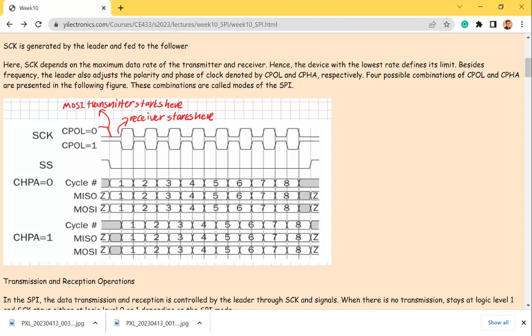Put the PN junctions in there and hold the charge using capacitors, and then send everything out to the ADC to digitize it. And we would have to implement some digital ports on the chip to send out the data, it can be to an FPGA, and then send it to a monitor eventually. That can be a very good project.